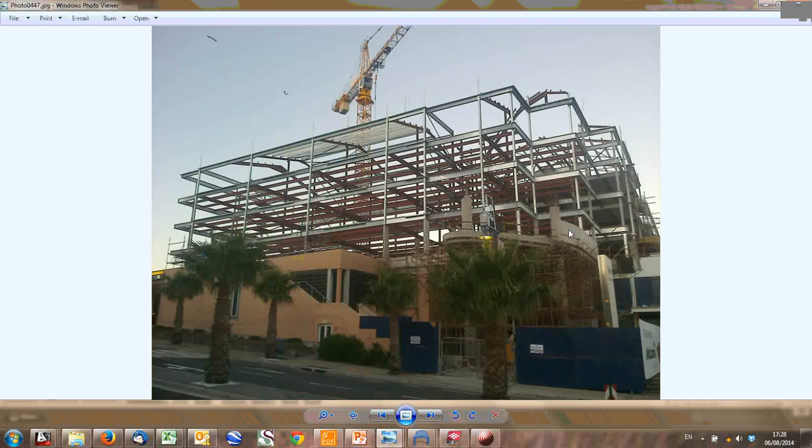Let's say a lift shaft, which is a nice stiff poly structure. To analyze every little bit and piece is going to be a nightmare to get the loads on your lift shaft, wherever it is. So, you just take your tributary area and pressure and suction. You can quickly then get a horizontal load which you apply to your lift shaft, and you can size your lift shaft or your brace floor or whatever it is that provides lateral stability.